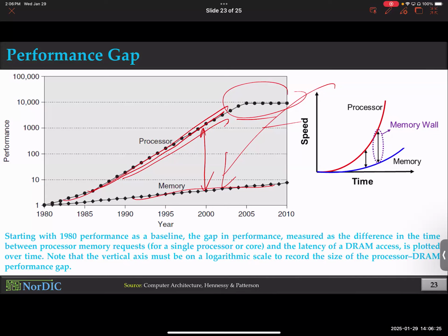When you read or write something, you have to flow current through it. No other option, right? So when current flows through something that has resistance, you create I squared R, a resistive drop, and over time, I squared R T. So you generate heat. And that heat is a problem.